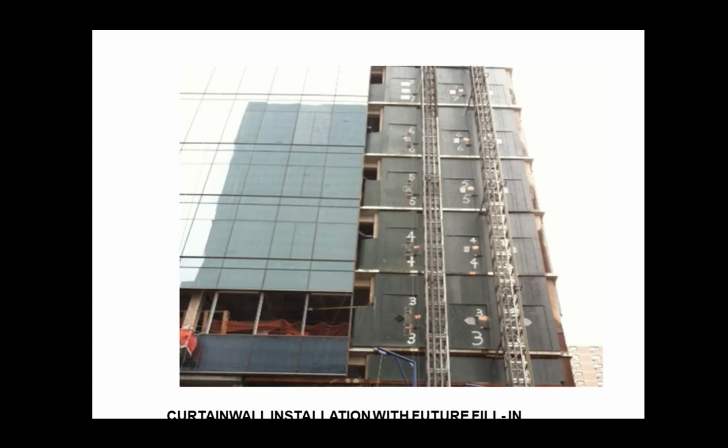All right, so this is a real example of that panelized type thing. What you see there are the hoist systems that feed your building. Okay, and you can see there's like a doorway at every floor of the building. So as they're building, they're going on up. And remember what we said the negative was for the hoist system is that you have to go back at the end, take down the hoist, and then fill in whatever exterior detail you're using, whether it's bricks, concrete, curtain wall, glass.